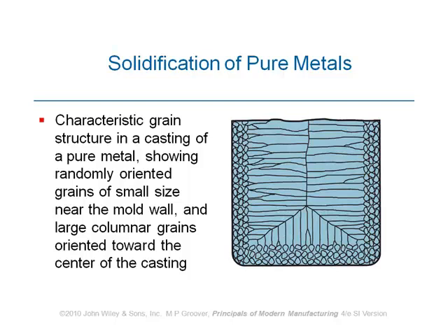As we move inward from the surface of the part, we see a different microstructure. There are very small tiny grains on the surface, and after a certain distance away from the surface, some different shapes of grains are produced. Indeed, they are long grains moving from the external surface inward. This type of growth of the grain is called dendritic growth. Dendritic.